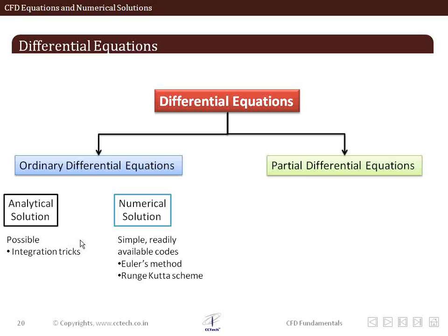In such cases, we can use some standard software packages which involve some kind of numerical scheme to solve these ordinary differential equations. We can use dynamic simulators available with commercial packages like MATLAB or Scilab. MATLAB has Simulink, and Scilab, which is an open source solution, has a dynamic simulator called XCOS. They use methods like Euler's method or Runge-Kutta schemes in first order, second order, or fourth order, with which you can find solutions to such ordinary differential equations. But for some simple problems, we can use hand calculations, and using some integration tricks, we can have analytical solutions.